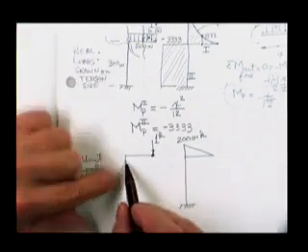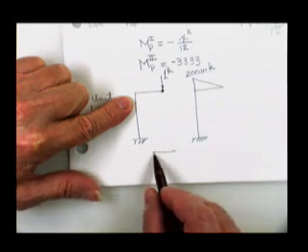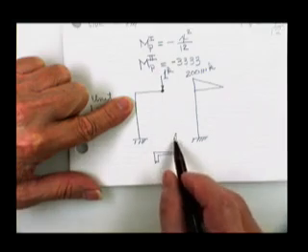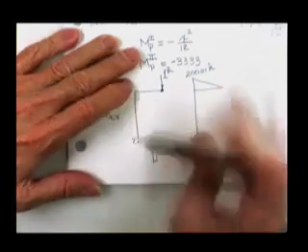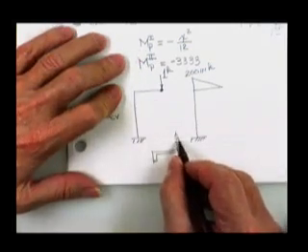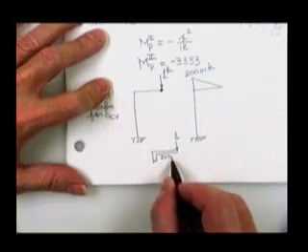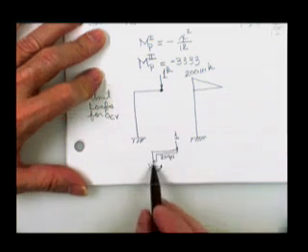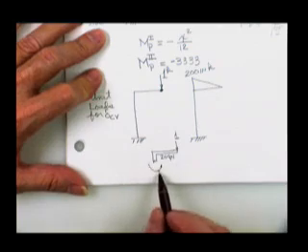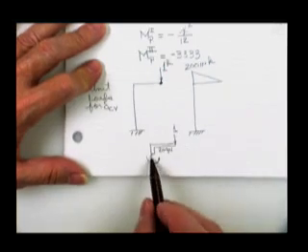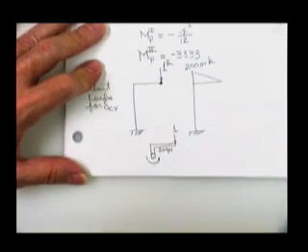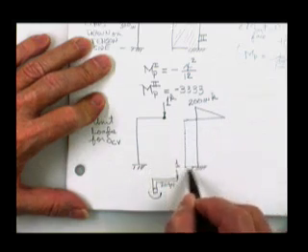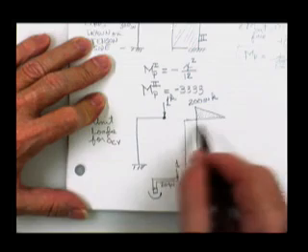And when you turn the corner, if you'd like to see a free body of that, it looks like that. There's a 1. This is 200 inches. And therefore the moment at this point will cause tension on the left-hand side, and the value of the moment is 1 times 200. And if you cut it a little longer, it's 1 times 200, and so it's constant. So your moment diagram looks like so.